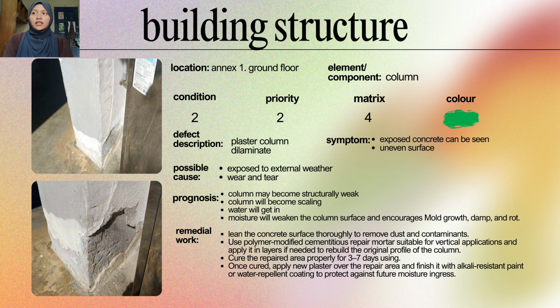Possible cause of this is exposure to the external weather and also wear and tear. Prognosis of this will be the column may become structurally weak, the column will become scaling, water will get in, moisture will weaken the column surface and encourage mold growth, damp and rot.